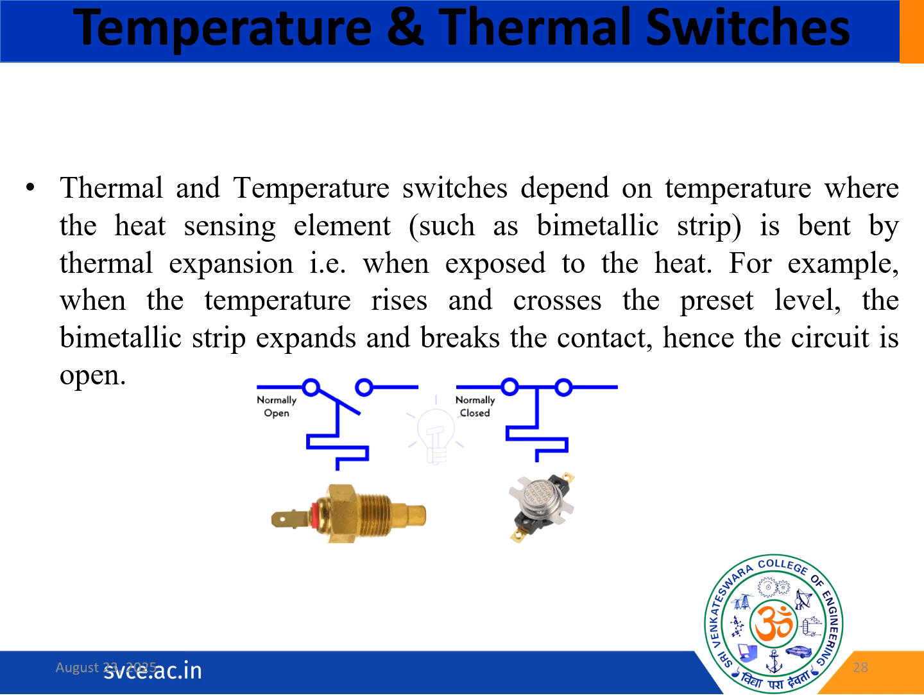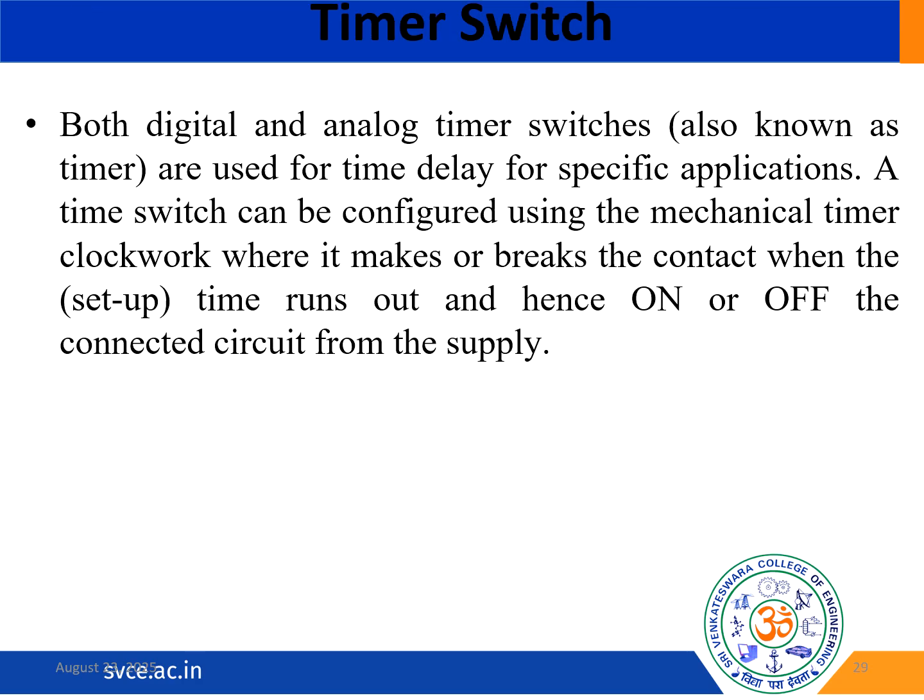These types of switches can be used in overheat protection in appliances, fire safety and alarm systems, and HVAC systems. These switches are valued for their simplicity, they are very reliable, and the operation is very passive. This makes them ideal for fail-safe thermal control in both consumer and industrial settings. So these are the basic operations, and we have completed how temperature and thermal switches operate.